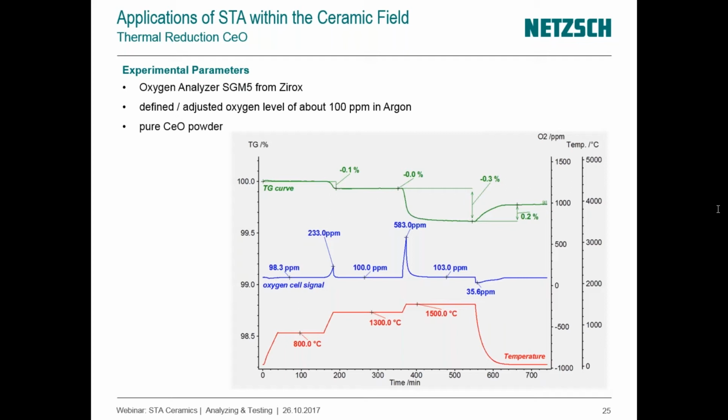There's also still the possibility to go to metallic crucibles, so typically platinum crucibles. Here's the question: if we have just pure lead oxide, most likely it will work with the platinum up to a certain point without any problem. But then maybe thermal reduction of this lead oxide could lead also to reaction with the platinum, but I'm not completely sure at which temperature you will face this problem. So here we must look at detail, so we will send you afterwards a more detailed answer, if this is okay.